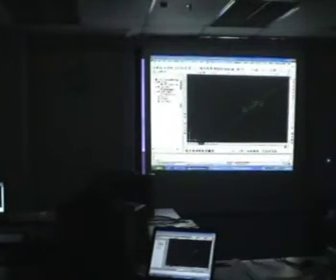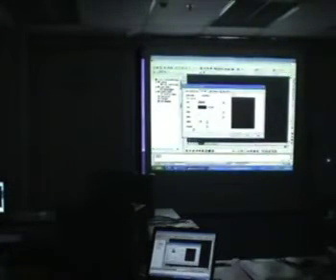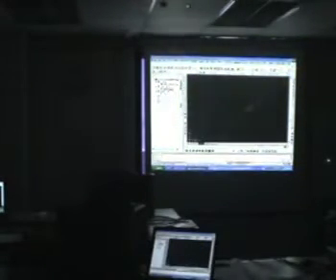Let's say I don't want so many decimal points, and I want a box around the text. You can go back to the Contour Style Manager. That's under Text Style. Precision is the number of decimal points, so I'm going to drop this to 0. And maybe I want to draw a border or label around the text. I'll just click OK. It will be updated for me.